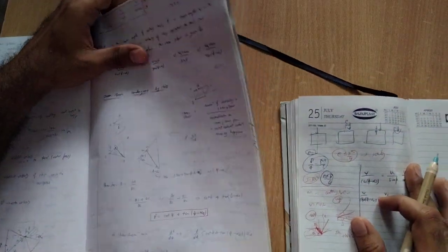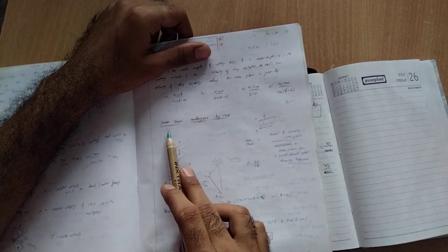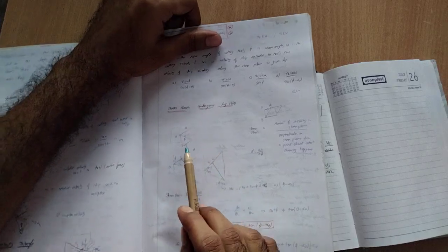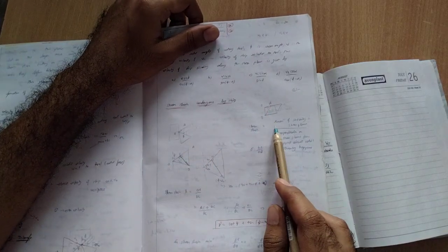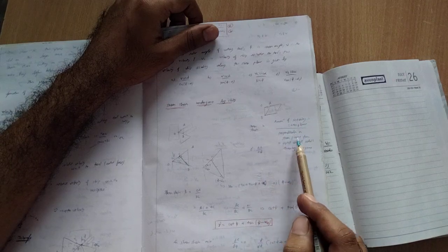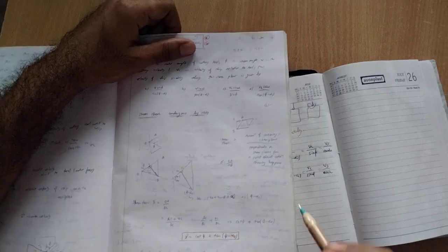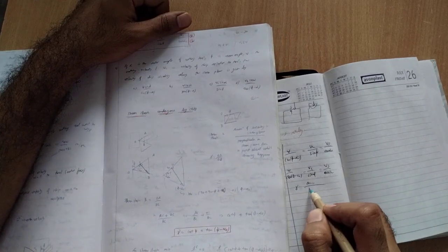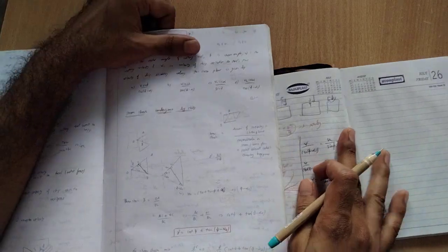The next one is shear strain undergone by the chip. Shear strain, not shear stress or anything else. You can see points O, A, B. Shear strain equals the amount of shearing in the shear plane divided by the perpendicular distance on the shear plane from the point where the shearing happened. It is a simple case: shear strain equals the amount of shear occurred in a plane divided by the distance.